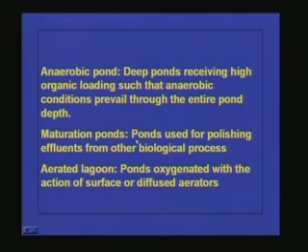And aerated lagoons are the ponds where we give artificial aeration, because the natural aeration that happens due to the oxygen deficit existing in the system may not be sufficient for proper treatment. So, in such cases we have to give aeration externally. Any pond where we provide external aeration is known as an aerated lagoon.